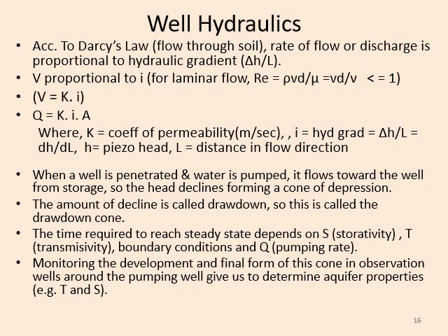When a well is penetrated and water is pumped from that well, water will flow toward the well from the surrounding area of influence, from the storage. So the piezometric head will decline or decrease, which will form a cone of depression.